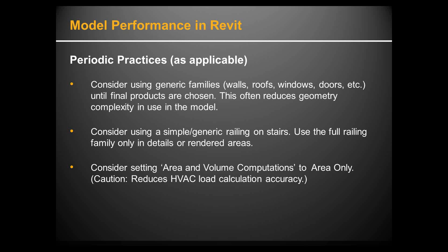If you need it sized and so forth, maybe you create a cube or a block that represents that object, or like Tony said, a very simple chair. And then in the Revit data on that chair, you put the more extensive information. But you don't need to have that chair all the way unless you need it for, say, a rendering or something. And then after that, get rid of it again.